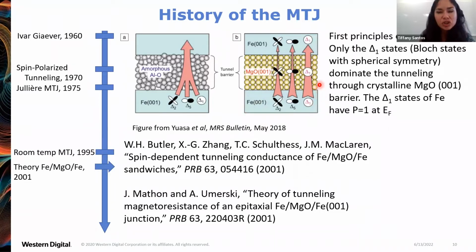And then in the MgO, it will have a lower tunnel barrier height, making it easier to tunnel for these fully spin polarized electrons. So it's a specific combination with this specific structure across the interfaces. But if you have this tunnel junction structure, then you could get very high TMR values approaching 1000%. So this was very motivating for experimentalists to pursue.